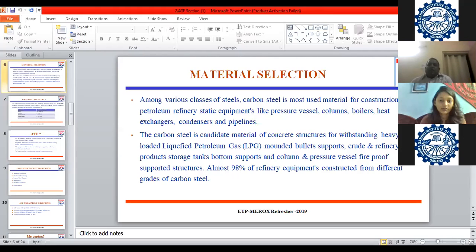plants. So when we are dealing with saline water, the chances of corrosiveness increase. And because of the sea-based plant, a corrosive atmosphere will be there. So we have to protect our equipment, our pipelines, our pumps, whatever assets we have. When we think about protection, then the thinking again comes to cost. So from the cost and protection point of view, the standard refinery decides that all the requirements have to be made from carbon steel.